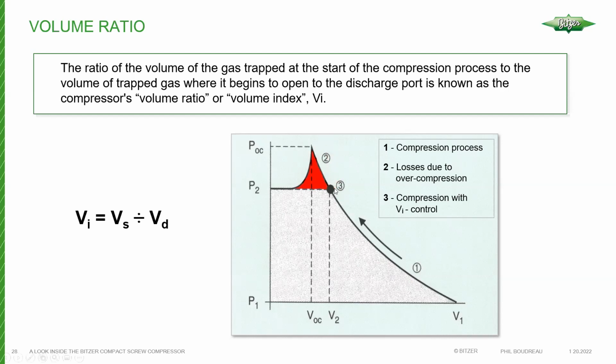And similarly, you can actually have under compression in a compressor for a similar reason, and then you're only using part of the screws, and you've actually got discharge pressure at times backing into the rotors. That may seem very difficult to imagine, but under compression and over compression are two very possible things that will occur with a screw, particularly when it's not designed to compensate for different pressure ratios.